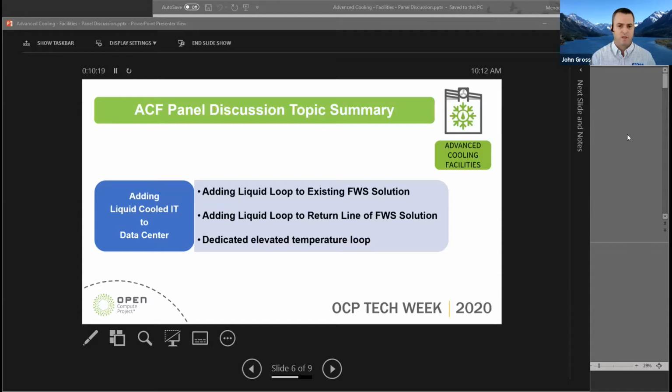So for example, in that separate high temperature plant that we designed, we had what I called building level CDUs that separated the chilled water system from the process cooling going out into the data center itself. So we actually had two separate facility water systems there. We did that because of the temperature delta incompatibility between the ITE solution and the chillers.